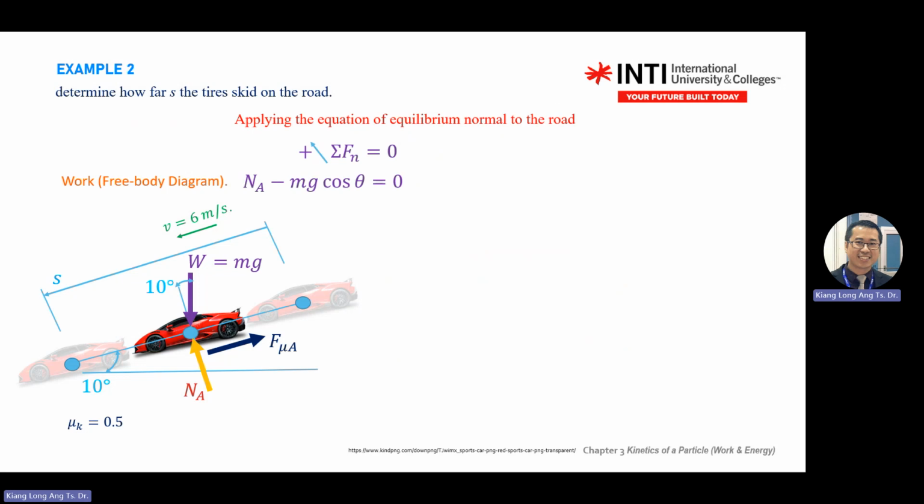Okay, so you do the equilibrium equation to find NA. To find NA, take all the forces in the normal direction, and you can put in your axes, Y and X if you want. So in this case, my normal force goes up positive. The sum of forces 90 degrees to the surface is equal to 0.